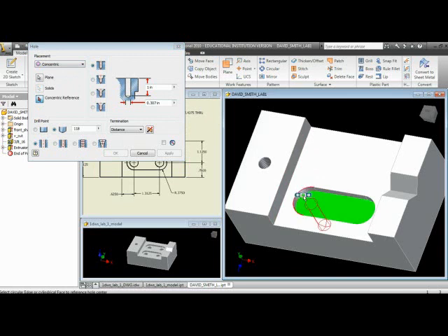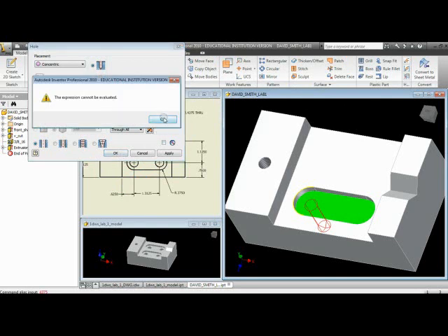Now the holes themselves, let's see, we got 4 times the diameter, 0.4375, so I got 4 holes that are 0.4375. They go all the way through, and they're concentric to the original circles that I put in. So I'll go into the hole command. I don't want linear, I want concentric. The first thing it asks me for is the plane.